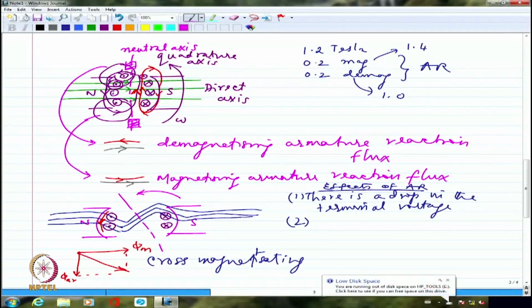Whereas now, I am definitely going to have conductors which are not carrying zero current and will be expected to change over because I have put the brush there. So I am going to have somewhat more difficulty in changing over the current from plus to minus or minus to plus, which we will look at with the magnifying glass in greater detail under commutation.